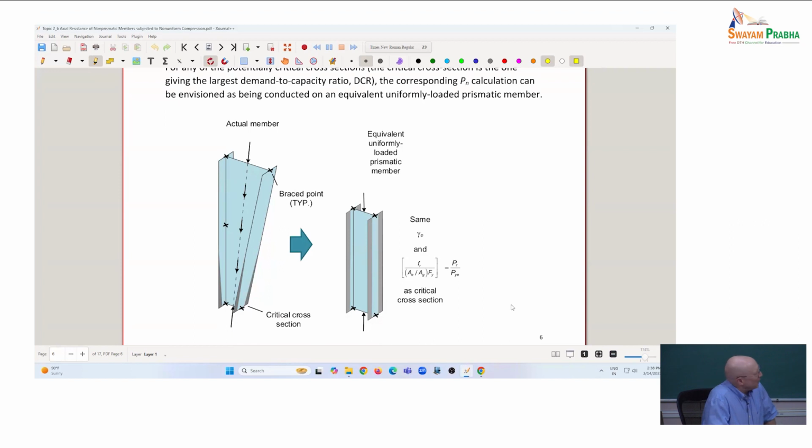so here, maybe we've got a tapered column like this, and sometimes if you look at a tapered column, if the web is really thin up there at the top, you might have such a significant elastic local buckling effective width reduction. Possibly that cross-section at the top might be more critical, but usually it's going to be the smaller cross-section at the bottom if the web thickness is constant along the whole length. And so you go to that bottom section, you get your